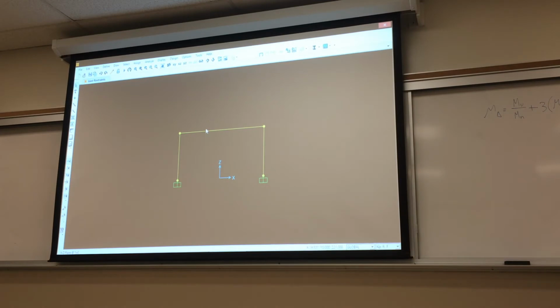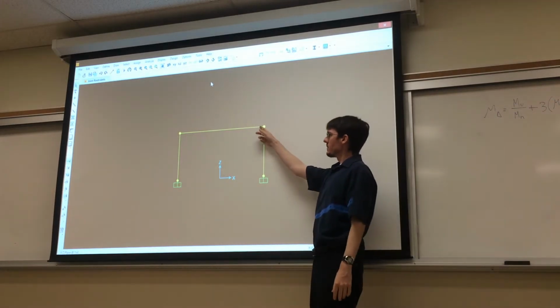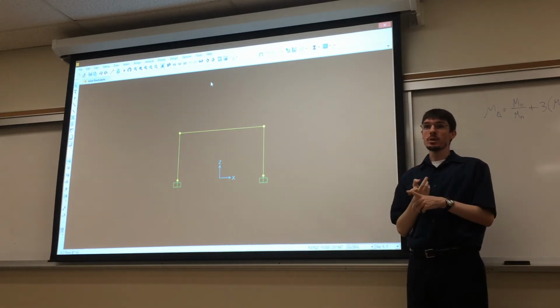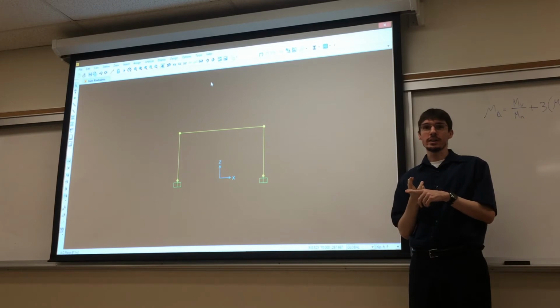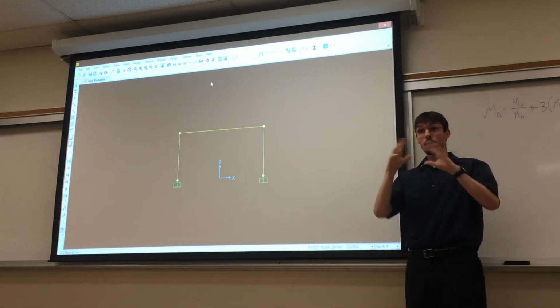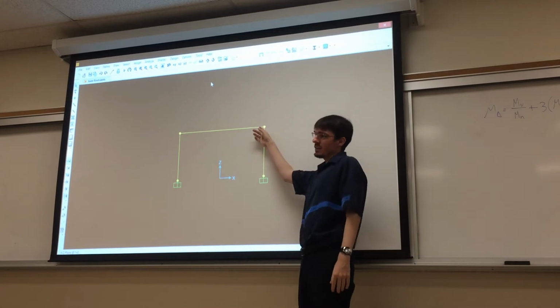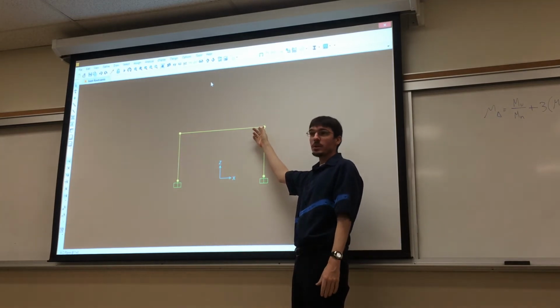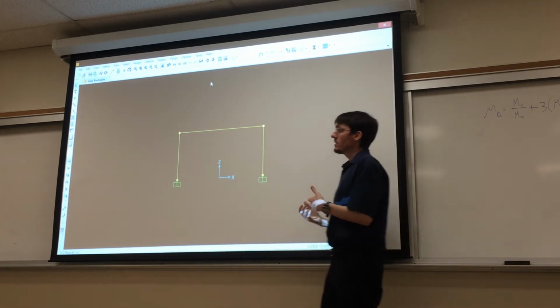The next step, essentially, is that we want to A, define the loads on this frame, and B, set up the geometries. There's something to keep in mind when you're defining the properties of this member: SAP doesn't really care what all the geometric details of this member are. It's mainly going to care about the geometric properties, i.e., what's the moment of inertia of this section, what's the cross-sectional area, all the properties you'd solve by hand for a section. Whether or not you give it that section directly, it doesn't particularly care. So you don't have to have a wide flange beam to represent a wide flange beam. You can come up with something synonymous for that, or you can define properties on your own.